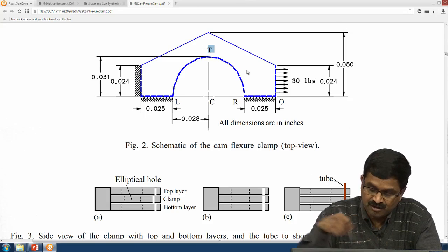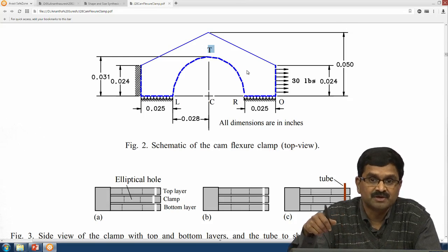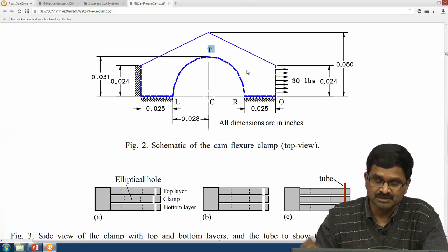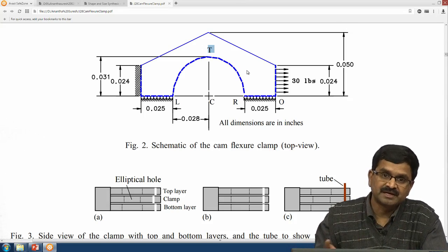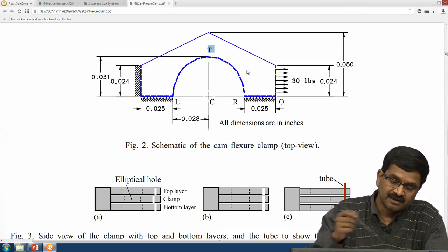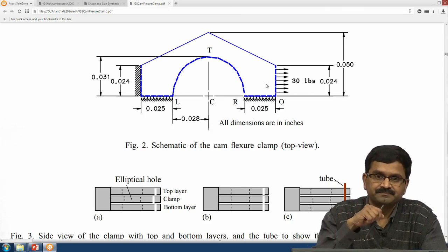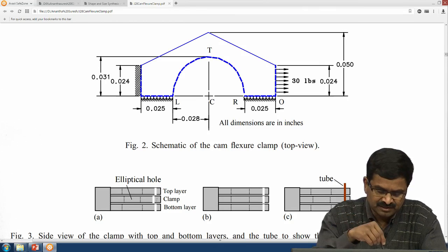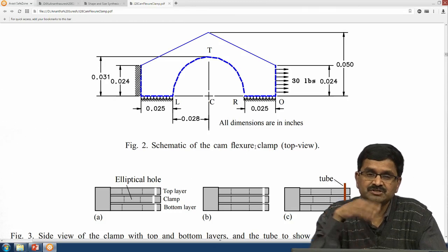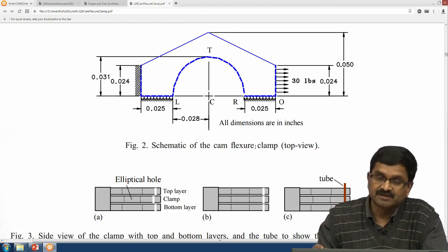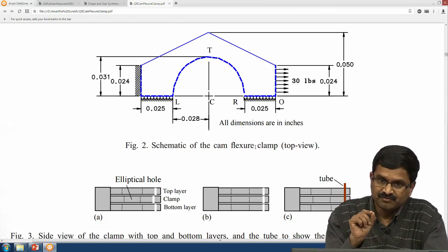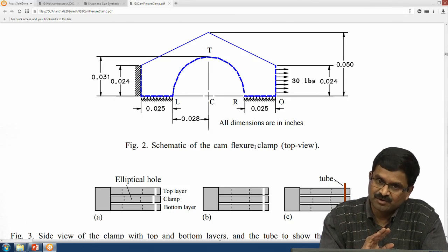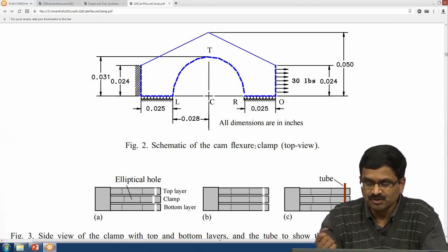Okay. And the force of clamping, they wanted a certain force value as well. So, you want to have so much clamping force, at the same time stress should not exceed a particular value, and a highly restricted design domain. If you fill that whole thing and try to move it here, and there is a little hole here that aligns, he had found that the stress will be very high when you want a certain clamping force. So, if you keep misalignment very low, your stress will be low, but you do not have enough clamping force.